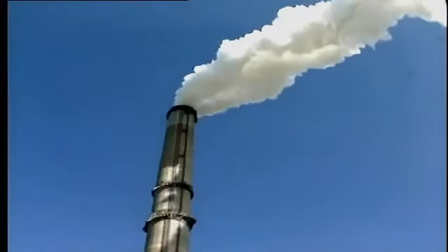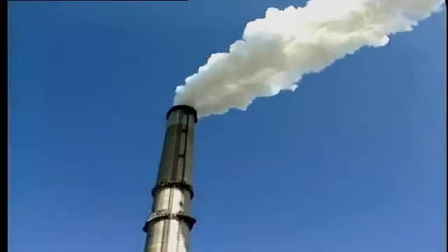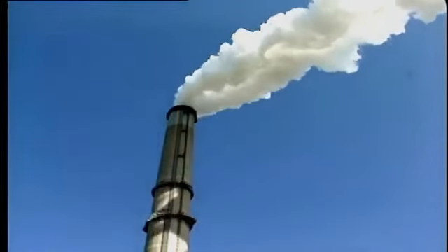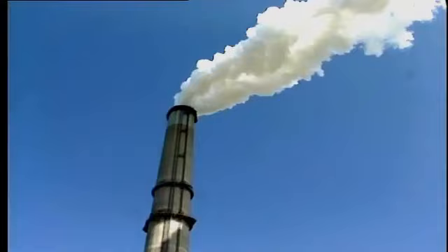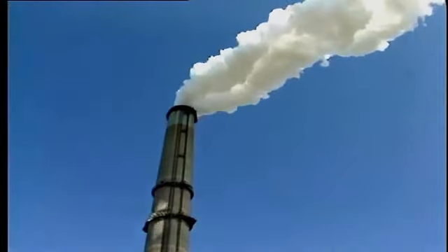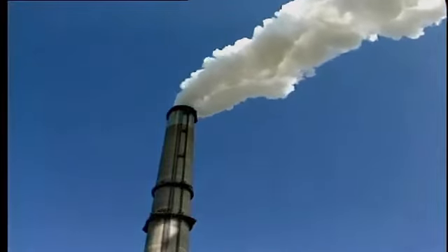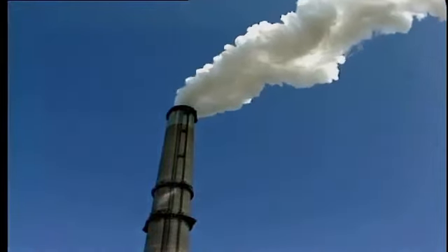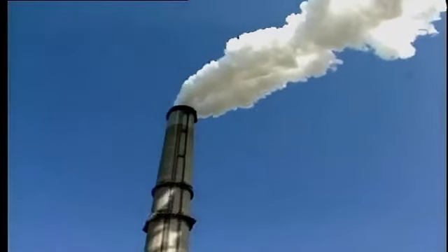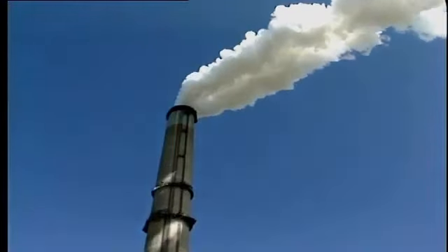In some power plants, a large quantity of water vapor may be formed in the flue gas scrubbing process and is subsequently discharged from the chimney. This is often regarded as a sign of serious pollution by uninitiated observers. In fact, the vapor is quite harmless, and it can be reduced by heating the flue gas to about 250 degrees Fahrenheit as it enters the chimney.